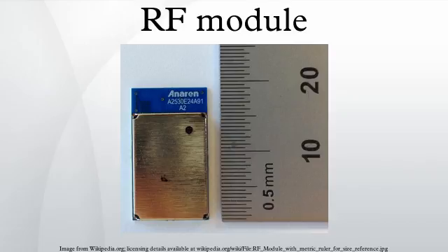System-on-a-chip module. An SoC module is the same as a transceiver module, but it is often made with an onboard microcontroller. The microcontroller is typically used to handle radio data packetization or managing a protocol such as an IEEE 802.15.4 compliant module. This type of module is typically used for designs that require additional processing for compliance with a protocol when the designer does not wish to incorporate this processing into the host microcontroller.